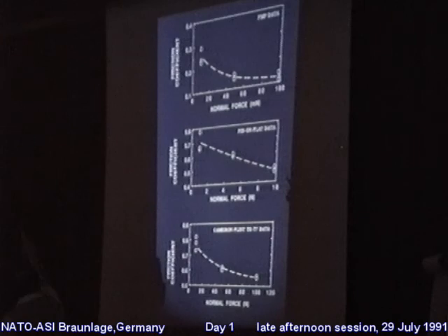But we notice then at 10 newtons down here on the pin on flat, now we remember we have the same ball diameter, the same oscillating frequency, the same normal load, just two different machines. At 10 newtons here it's down to about 0.5, 10 newtons here it's up to about 0.78, close to 0.8. And then it declines again as we up the load. So if you wanted to plot all these 3 on the same plot, you have the friction probe data at the lower end, and then almost parallel curves higher for the mid-sized machine and the heavy-duty machine.